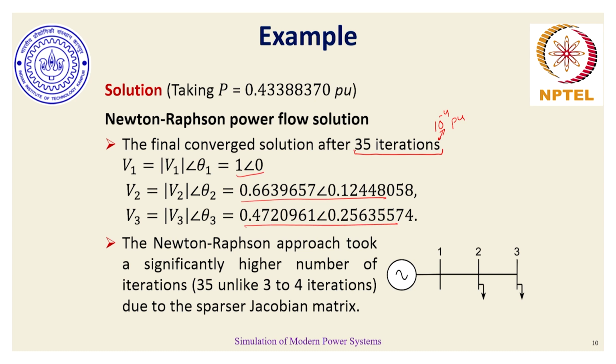Now, this high number of iterations itself is an indication that Newton-Raphson is having a hard time getting the solution of voltages for this 3-bus simple radial single phase distribution network. The reason is that the Jacobian is highly sparse.